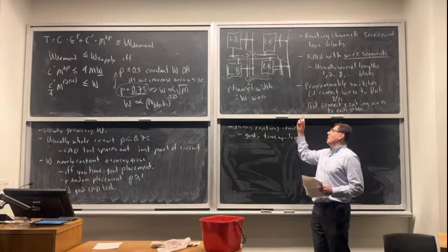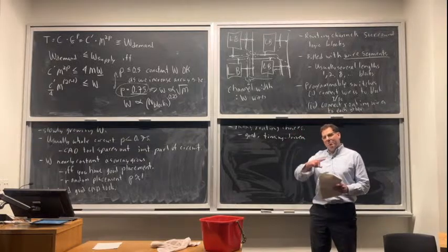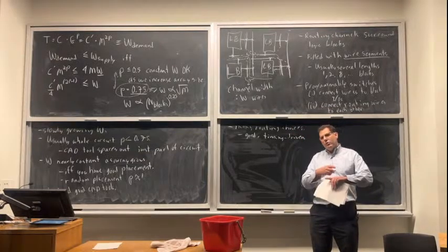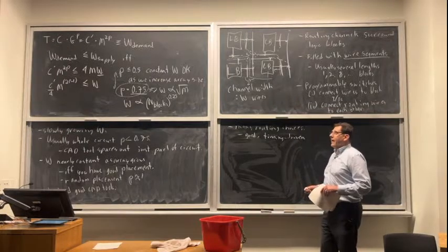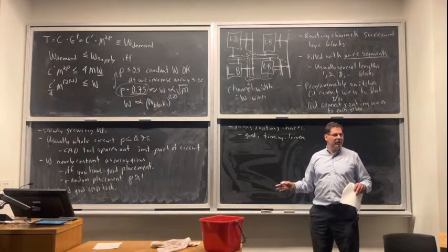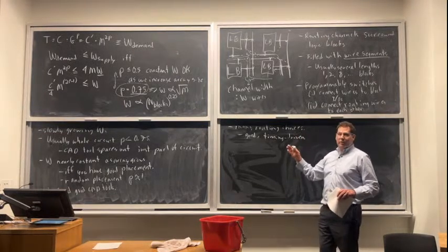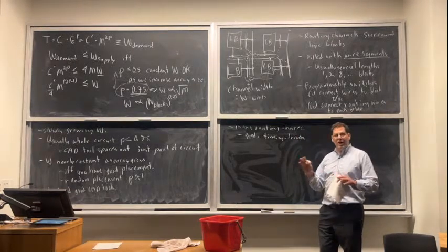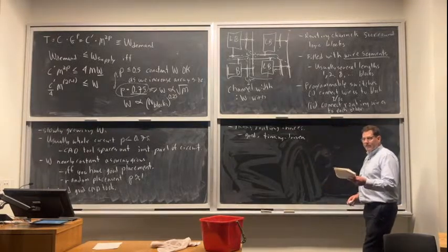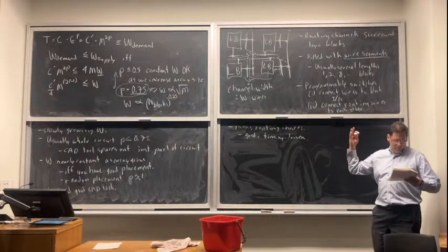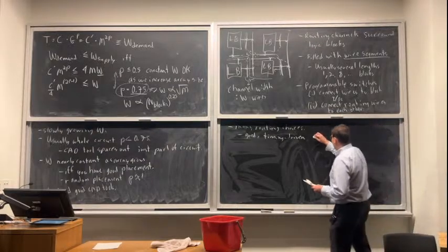That's really important in this kind of architecture because there will be some paths that are fast. You know, they use a small number of wiring segments that are the appropriate length and so on. And there'll be a lot of paths that are not fast. So if you have a routing algorithm that doesn't do a good job of prioritizing who gets the fast routing and what all the choices are, you'll get a very slow result. So you need good timing-driven routing.